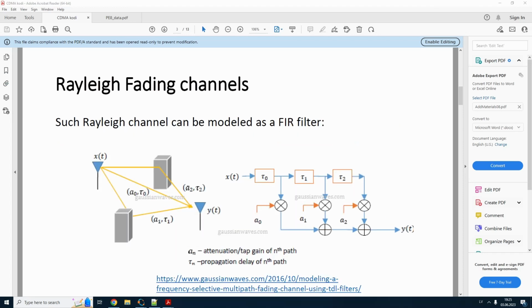Now we have been so far multiple times simulating this channel, Rayleigh channel, as a finite impulse response filter. So we specified some impulse response. In this particular case of this picture, it's specified as A0, A1, A2, so an impulse response with 3 samples. That's exactly those numbers we've been using for the Viterbi algorithm, direct feedback equalizer, MSE equalizer, and so far you always had around 3 values in your impulse response as well.